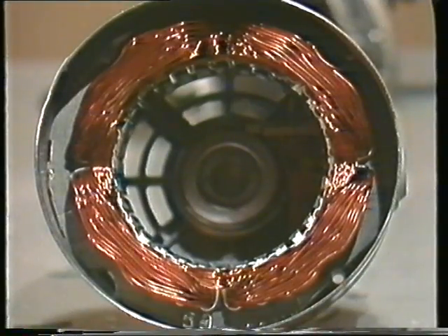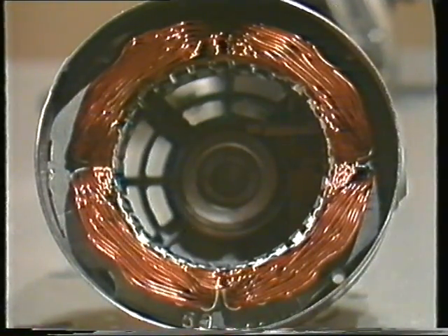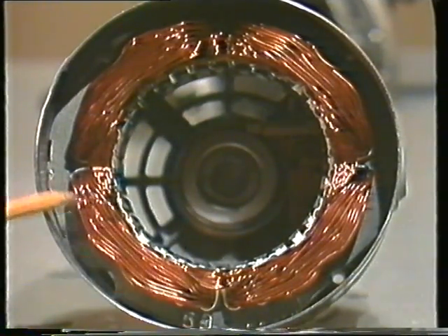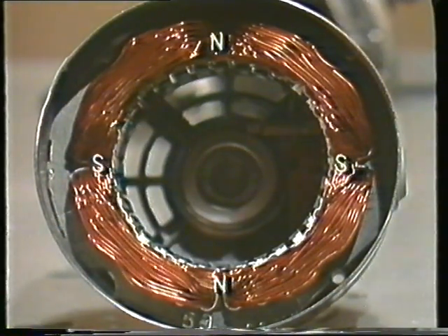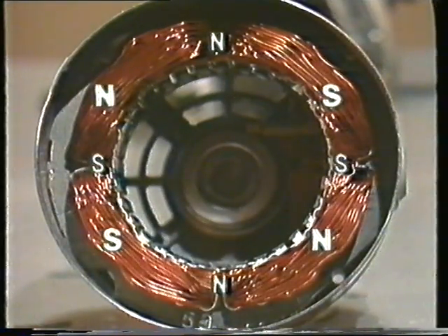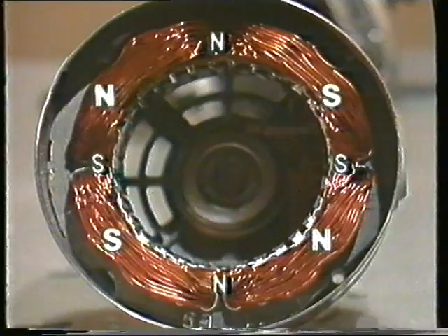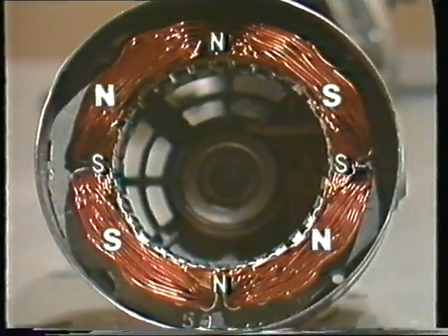To get them started in the right direction, most single-phase induction motors have two sets of windings, a set for running and another set to help during startup. The start windings are spaced around the motor, so their magnetic poles are between the poles produced by the run windings. There are several types of single-phase induction motors using this basic arrangement.